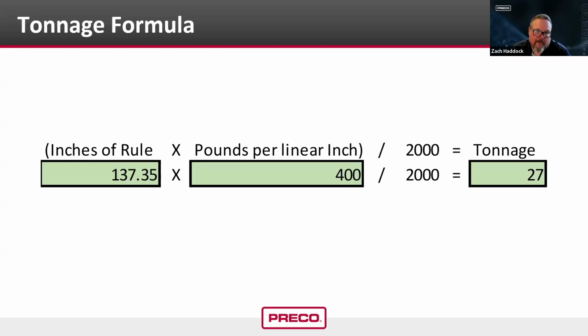If you use 400 to 500 pounds per linear inch, and then use my 80% rule, which we're going to talk about, you will be in the ballpark for most materials. Most materials. You've got to bear in mind, though, the outliers like the abrasives, the steel scrim, gasket materials, things like that. But in general, just for general quoting, ballparking, hey, do I have enough press for this? 400 to 500 pounds per linear inch will work for you.